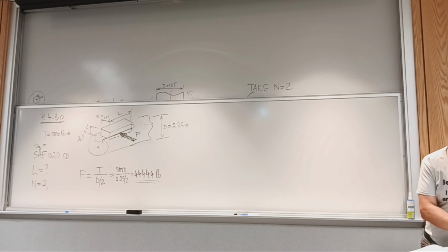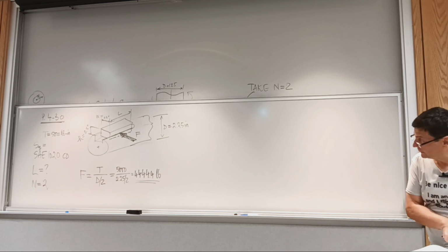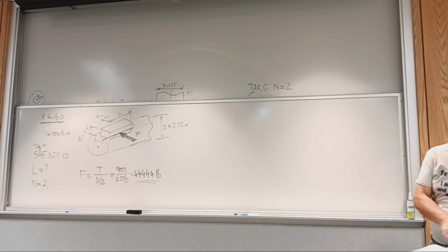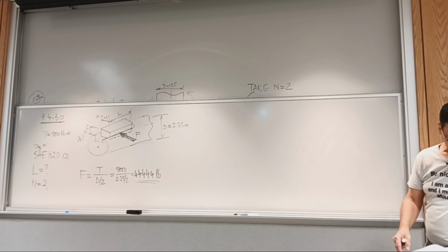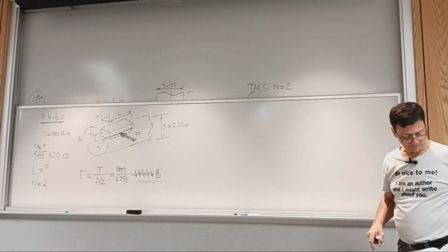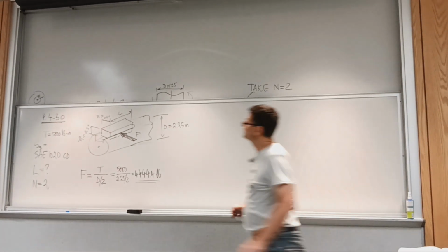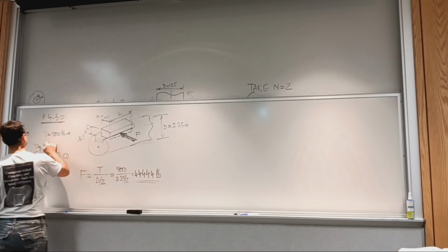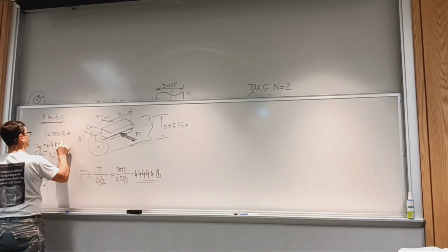The third was low carbon steels, plain carbon steel. So the yield strength is 440, we need KSI, so 64 KSI. Percent elongation is 20, a ductile material. So 64 KSI, as expected.